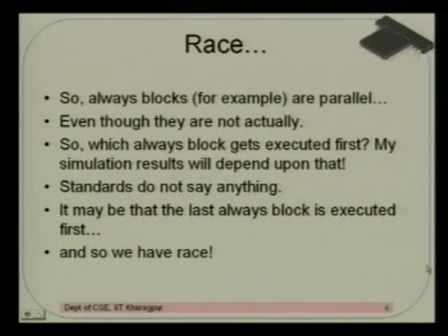So what is the problem? The problem is race. If there are two blocks and I do not tell you properly which block comes first, then you have the problem of race, because you do not know which block is going ahead. Therefore your simulation time and the real hardware that you have in your mind can have a mismatch. So you have to be careful.